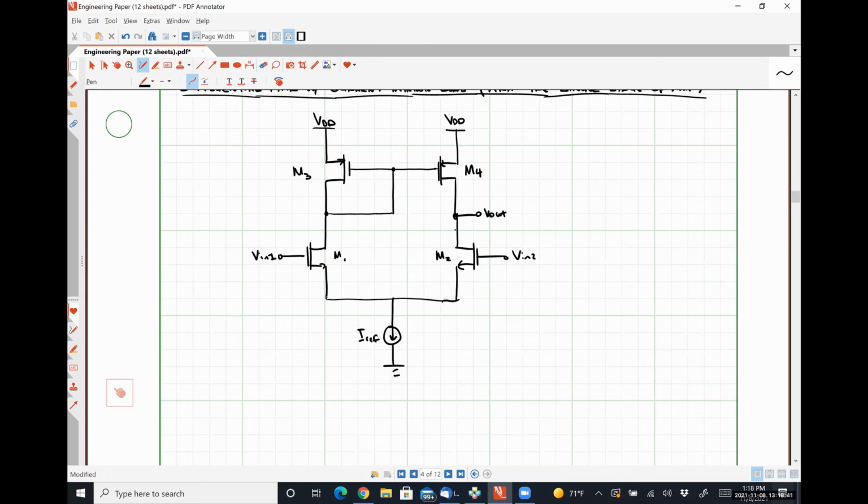Now, one drawback of this approach is that our circuit is no longer perfectly balanced like we had before. We wind up getting a single-ended output out of this system. By that, I mean we only have one output node that we have to worry about. Output voltage is measured with respect to ground as opposed to measured with respect to another terminal voltage in our system.